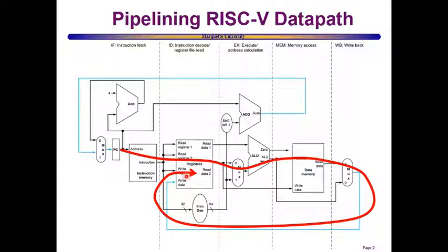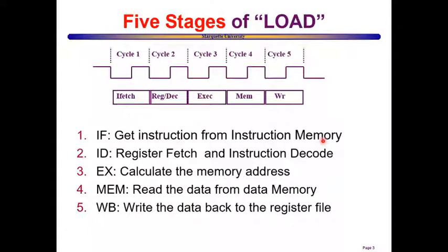The idea of pipelining is to split this path into a number n of balanced partitions, then insert pipelining registers at these cutting lines, and clock the new design at a clock frequency that is n times faster than the initial clock frequency.